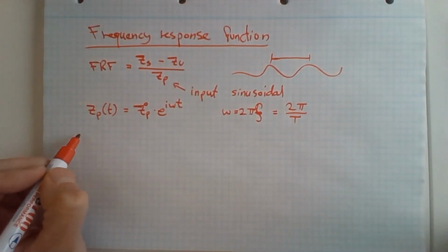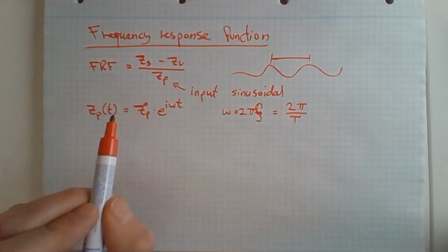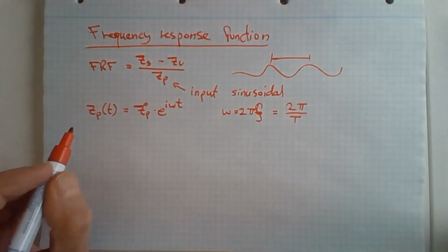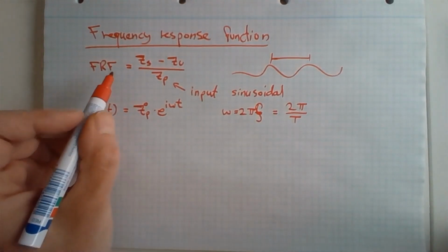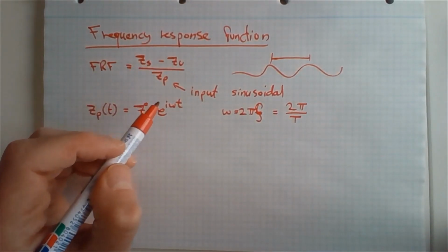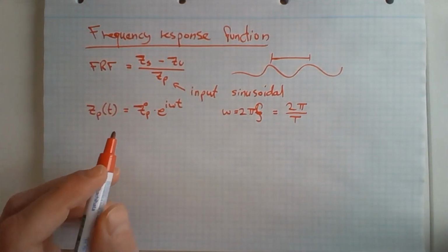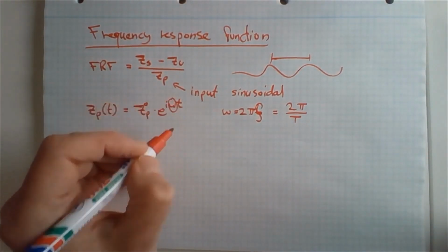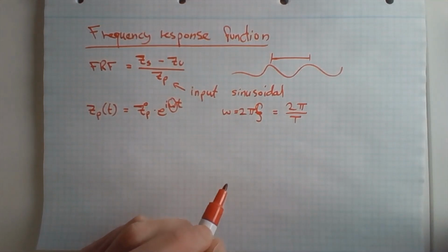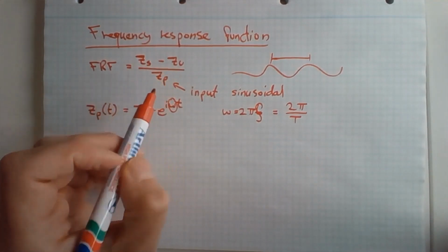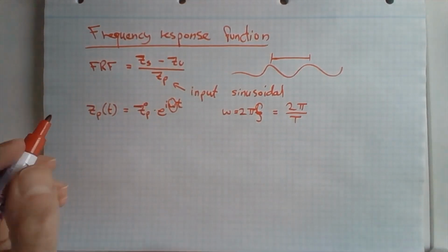We know that if a sine pavement is traversed by the IRI quarter car model, then the two masses, after a steady state has been achieved, would also vibrate with the same angular frequency as the pavement. There would, of course, be a different amplitude for each mass, and also some phase lag. Let's write this in general terms.